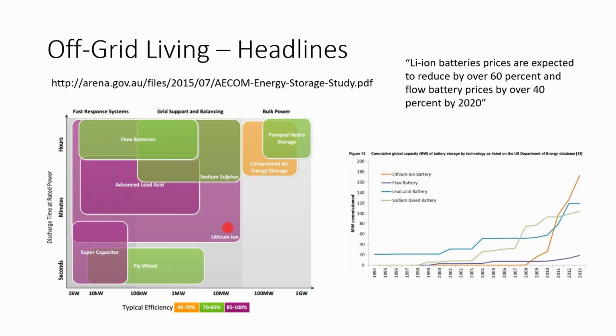But out in California, you not only have high demand charges, you also have high energy charges. So you don't want to just be concerned about the kilowatt component of the bill. You also want to be concerned about the kilowatt hour component of the bill.